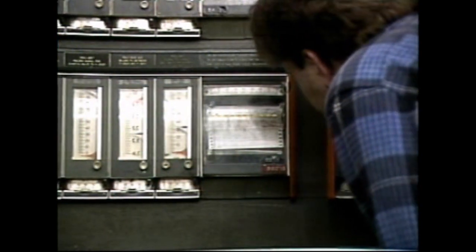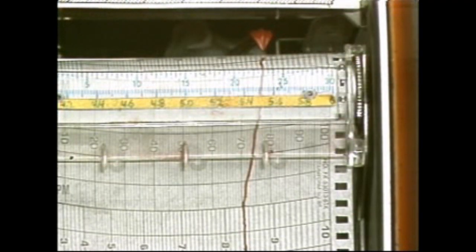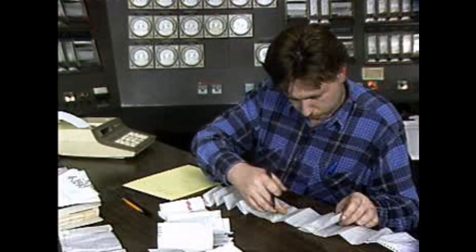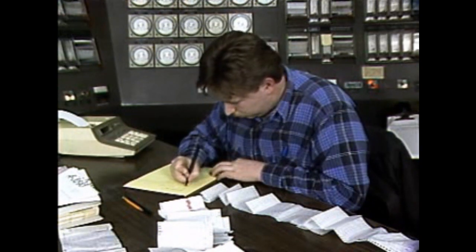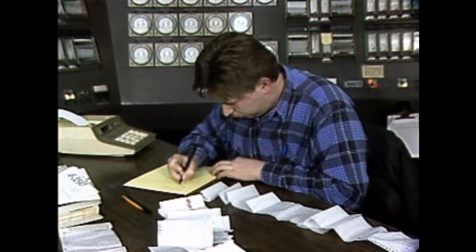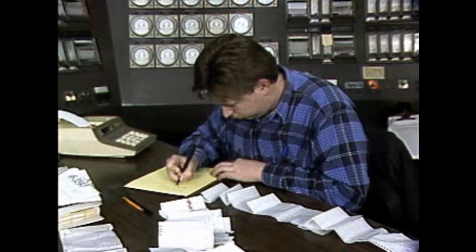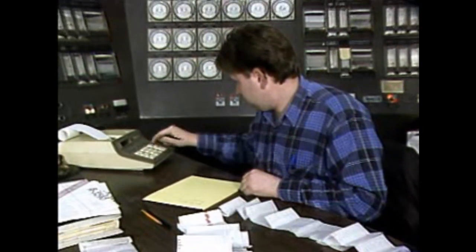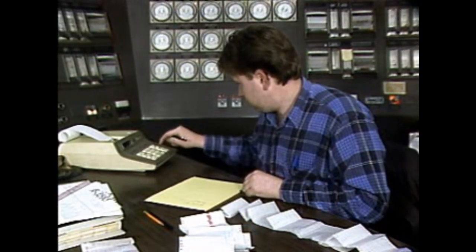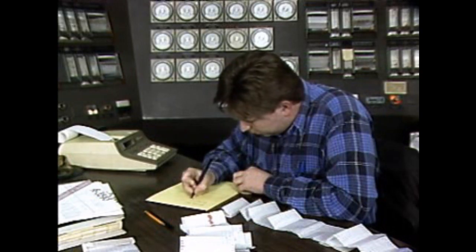This control room operator, for instance, has noticed that the reading on the chart for cooling water temperature has been steadily increasing. The first step is to determine the meaning or significance of the trend. From his knowledge of the system, the operator knows that a continuous increase in the temperature of the cooling water could cause problems. Equipment could overheat and be damaged. Process operations could be disrupted, and product quality could suffer.